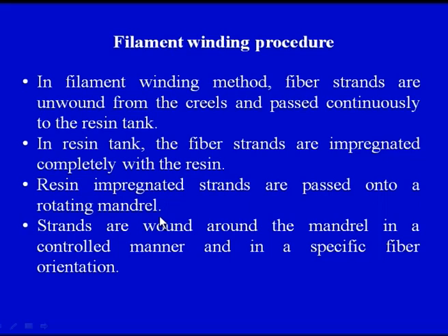One thing is important to keep in mind, that the mandrel is rotating and it is causing a tension in the fiber, so that the fibers are pulled and they are getting wound over the rotating mandrel. Strands are wound around the mandrel in a controlled manner and in a specific fiber orientation.